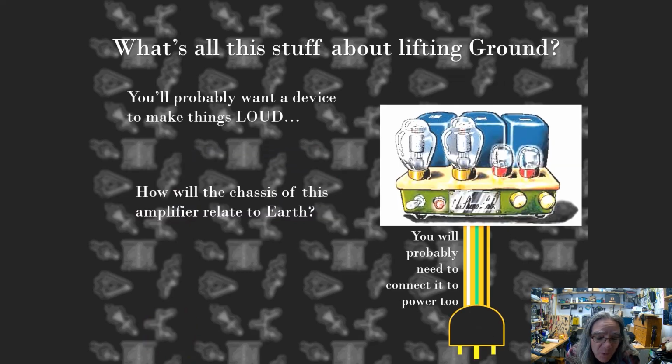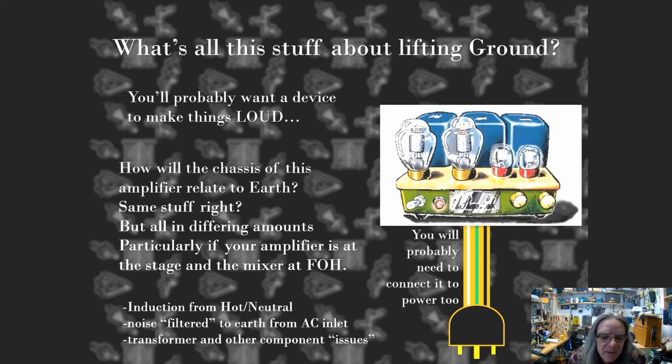So we probably want a power amplifier too. Now maybe this is built in the speakers, maybe not. I put one on here that's not built in. Right, we're gonna have to plug that into power, same as we do everything else. So the same things are going to happen, right? We have to have that power connection. All those same currents, all those same things are going to cause current to flow through our earth wire.